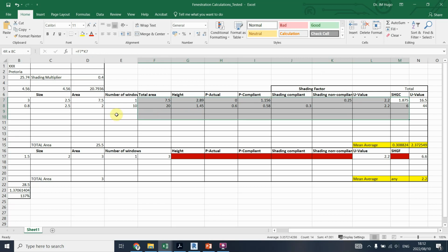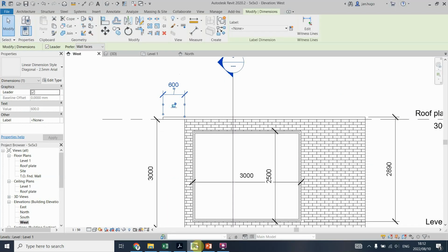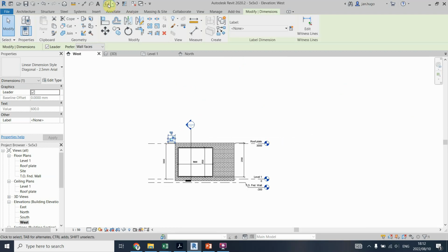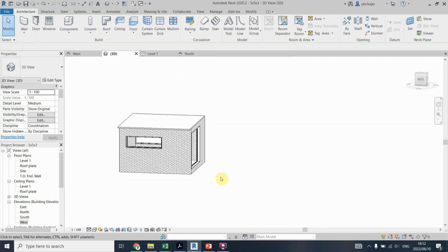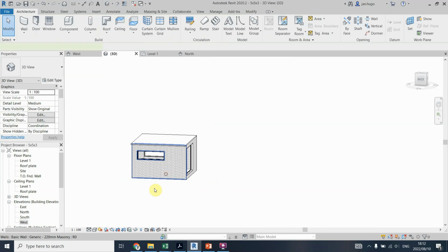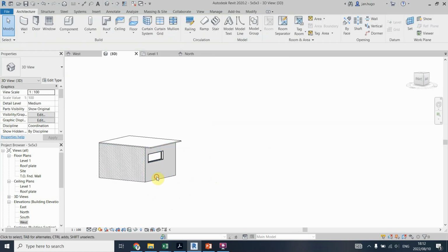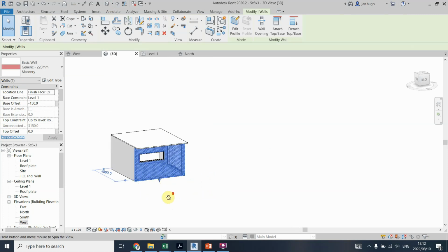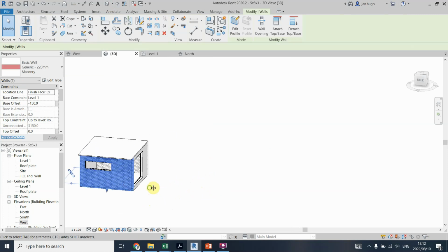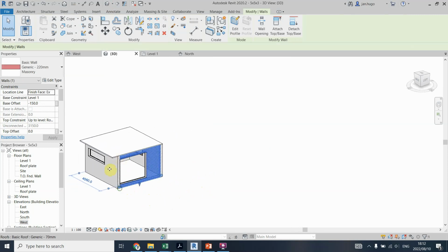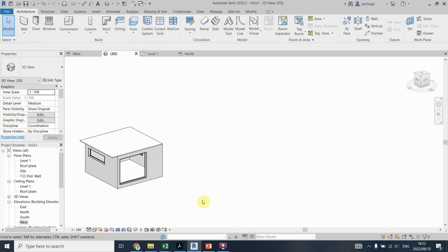So that's the thinking behind the mean solar heat gain factor. So it doesn't calculate that for every single window in the end. In the end, it says, okay, I now know that you've designed this building, but I'm going to take the mean, the average, for all your north, northeast, east, west, northwest windows and calculate that.